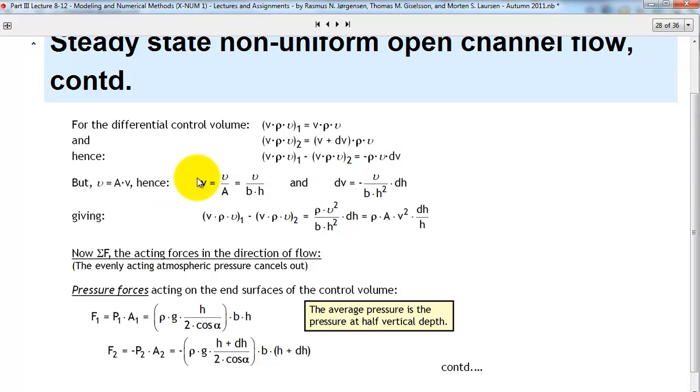And of course, if you want to find the speed of the water, let's assume you had something in the middle of the stream and you looked at that little P or something, the speed is this one. And there you need to use flow rate and divide it with the area. Then you know how much will be penetrating the area per second, or how fast it will pass through. I think that's the easiest way I can explain it.